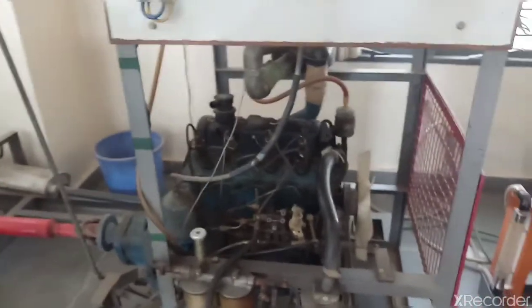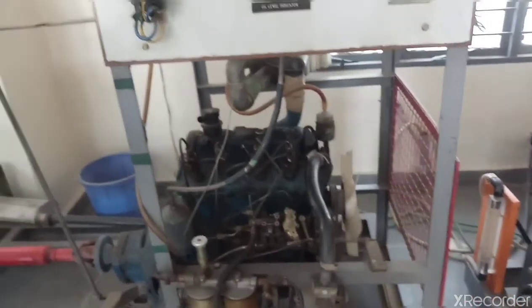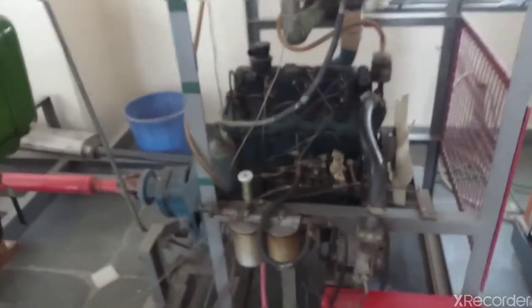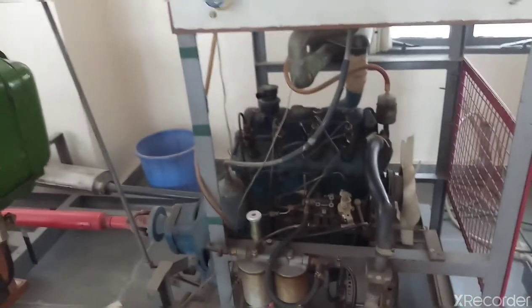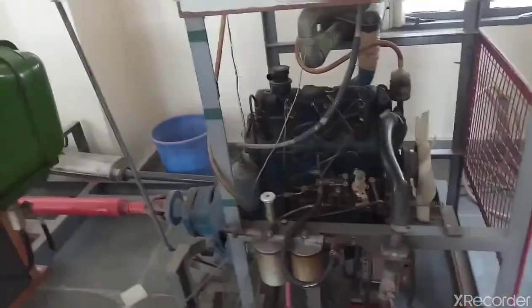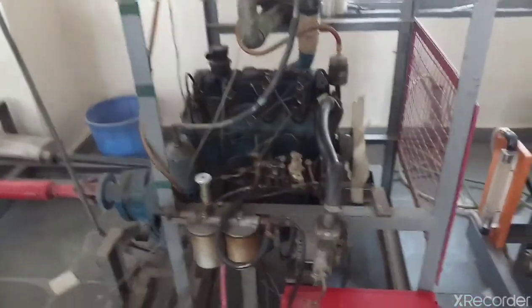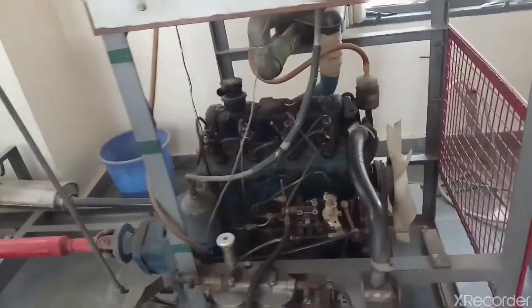So that is how we conduct the Morse test experiment. The ultimate aim or objective is to find the frictional power or indicated power. Once you know the BP, then you can find the other powers from the relationship. We know that IP is equal to BP plus FP. So from that you can always